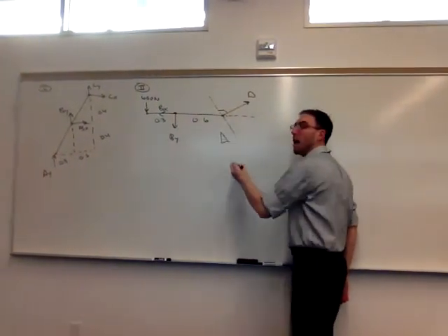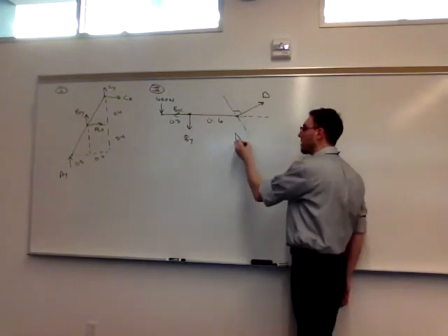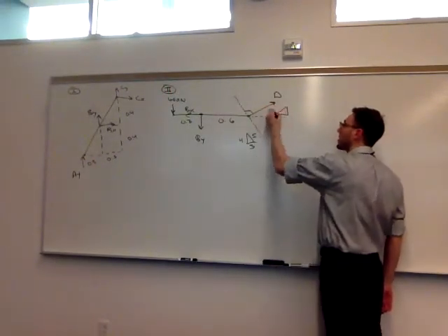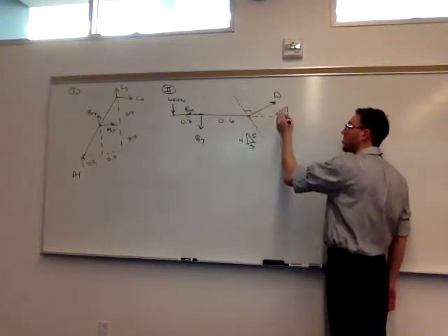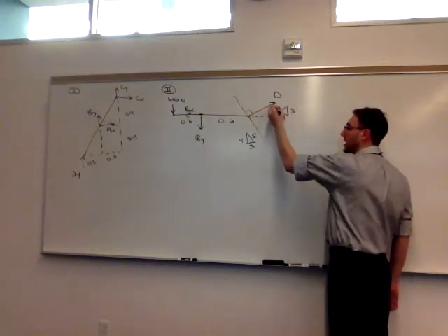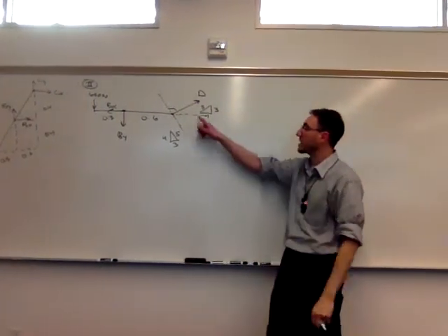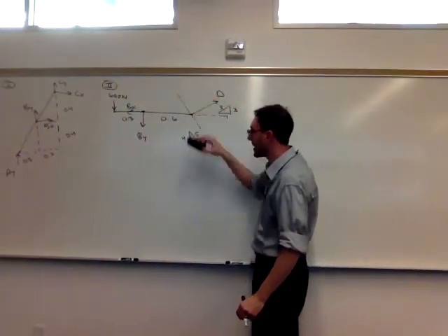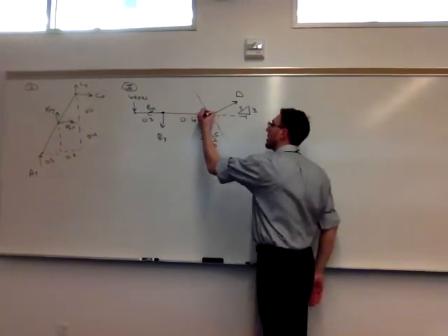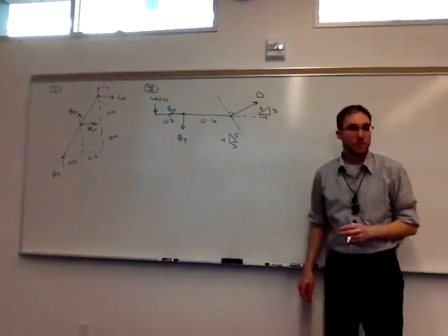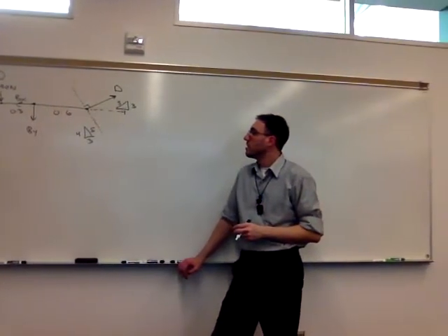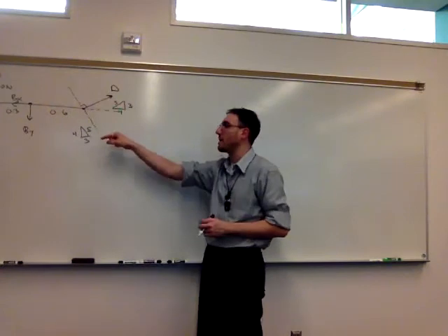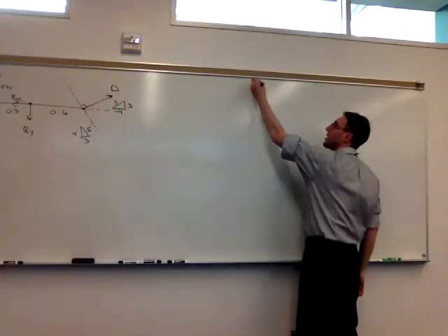So if this line is making a 3, 4, 5 triangle, with 3 as the base, 4 as the height, then this force must be the complement to that, which would be 4 as the base and 3 as the height. Right? So it doesn't look like it, but this is perpendicular to that CDE axis. So I know the direction, but it could be up and right or it could be down and left, and we can let the equations tell us which it is.